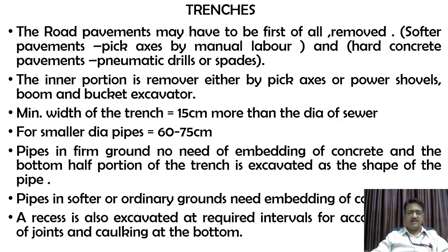Now the next part is with respect to the trenching, or trenches. For these particular trenches, the road pavements may first have to be removed. Softer pavements are removed by pickaxe or manual labor, and hard concrete pavements with pneumatic drills and spades. Here you need to dig up, and that is nothing but the trench. First you have marked out everything.